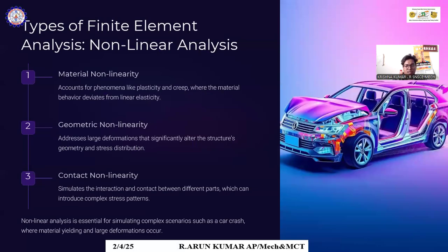And what about non-linear analysis? Material non-linearity accounts for phenomena like plasticity and creep, where the material's behavior deviates from linear elasticity. Geometric non-linearity addresses large deformations that significantly alter the structure's geometry and stress distributions.